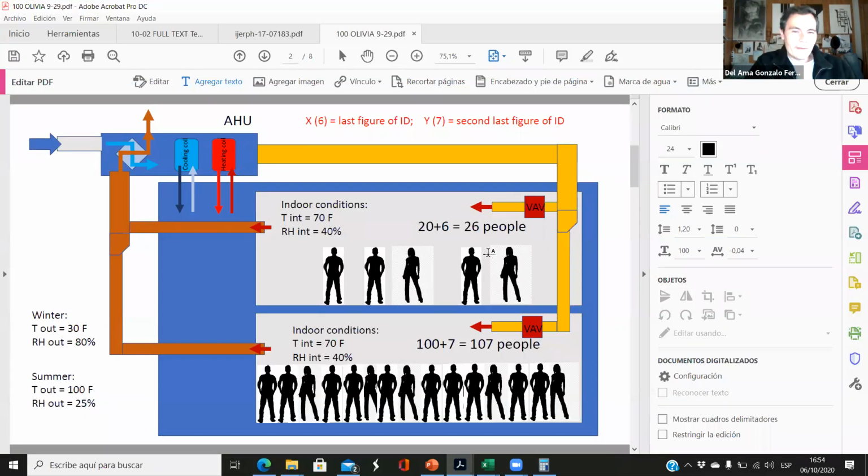Stagnation means that the air is stopped. And this is not pleasant because we are not renewing the air. We are not getting rid of the exhaust air, and we are not supplying enough air. Okay, so when that happens, we don't have comfort, and eventually we will have bad indoor air conditions. So the speed has to be within limits, so that we don't hear a lot of noise because of the high air speed, and we have enough ventilation and the air goes from this diffuser to that diffuser, because the air speed or the air velocity is good enough.